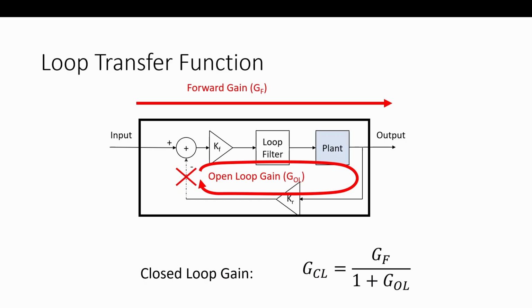When I make control loops, the worst thing is sticking some arbitrary filter inside your loop, because it's competing with your loop bandwidth. Putting an FIR filter in your loop that has a large delay is a bad idea. Let the loop filter itself clean the signal.